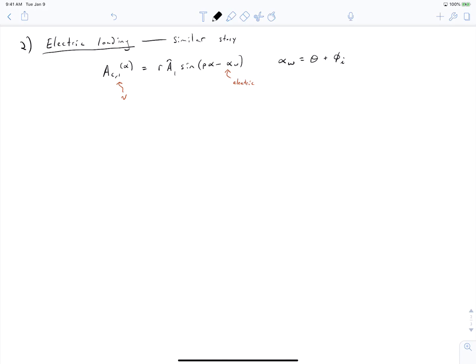And in order to create this rotating surface current, we talked about it in terms of a three-phase winding. And we've also mentioned in the past that this could be any number of phases greater than 1. So it could be a 2-phase winding, it could be a 4-phase, a 5-phase, a 6-phase. But for our purposes, the 3-phase winding is the most common, and so that's how we will continue to develop this. And as an aside note, the way we denote phases is with the variable m. So in this case, m equals 3. So our 3-phase winding expressions, we had written this out in terms of the fundamental as the following.